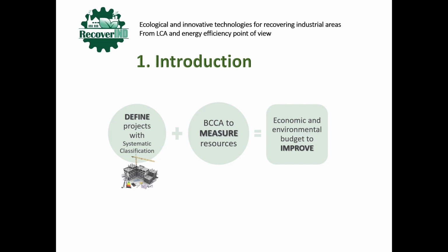It's to use the budget and the project itself, that information. For that, we can employ the systematic classification of construction works that allow us to define every element that is part of the construction project. Then we have to measure those elements to determine the quantities, perform the quantity surveying of that project.